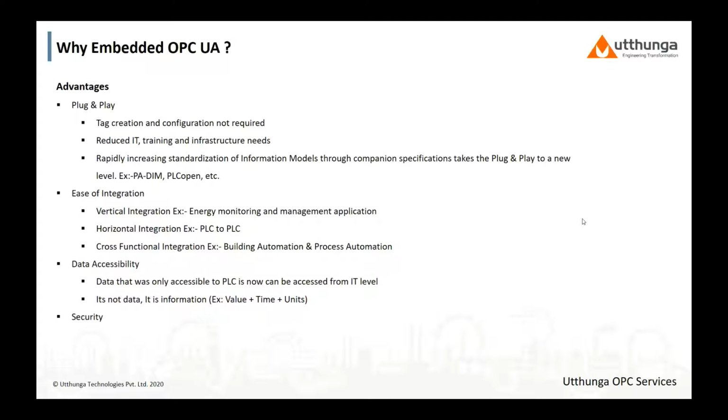For example, if you have any PC with a simple Modbus master program running on it, you can connect to the network and send commands to the Modbus devices, and they'll happily accept them. That's a very huge security risk. So OPC brings in security for the data in terms of authentication, authorization, encryption, everything.